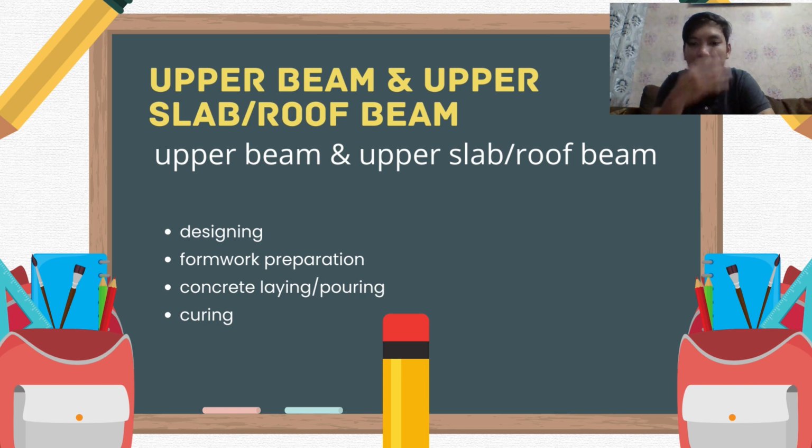Construction sequences of upper beam and upper slab or roof beam. First one is designing. Designing is the phase where the engineer will design the size of beam, the size of slab, the number of reinforcement bars, and the size of reinforcement bars. Then formwork preparation, and then concrete laying or pouring, and then the last one, curing.